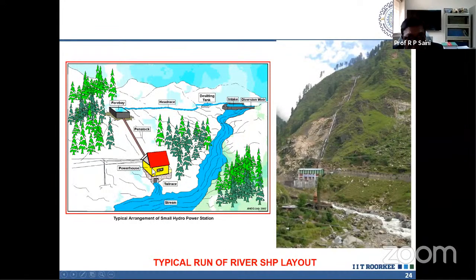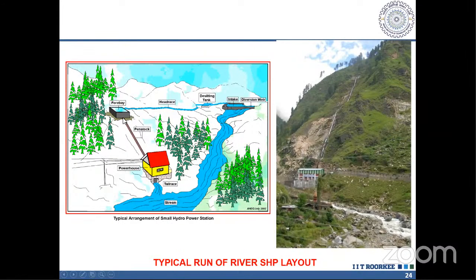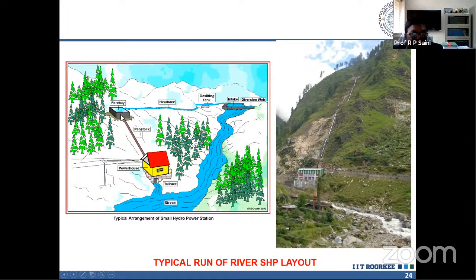Another purpose: sometimes when the water is flowing in this direction under pressure and suddenly the machine is stopped, by any condition, what will happen? The back pressure will travel in this pipe. Suddenly the pressure will go back. When it comes over here, if you don't have any cushion, this water will be splashed out of this tank.